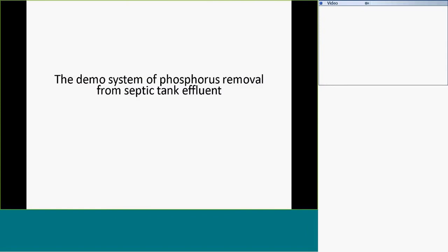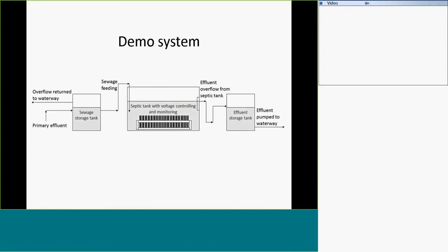And then we demonstrated this process in the septic tank. Sewage was lifted from the waterway underground to the temporary storage tank, and then goes through the 300-liter pilot-scale septic tank. We collect the influent and effluent and test the water quality every day, except for the weekends.